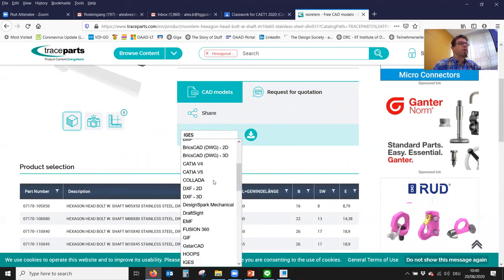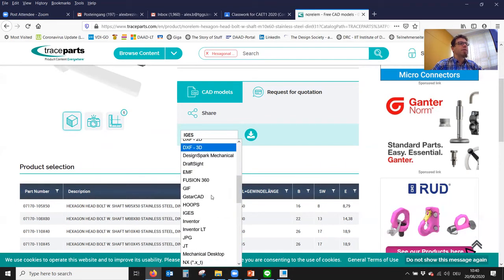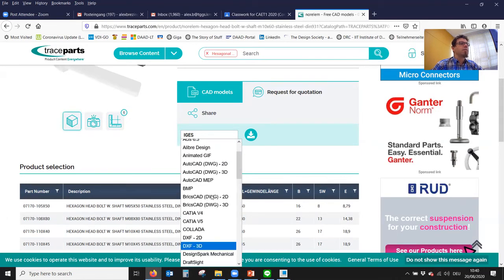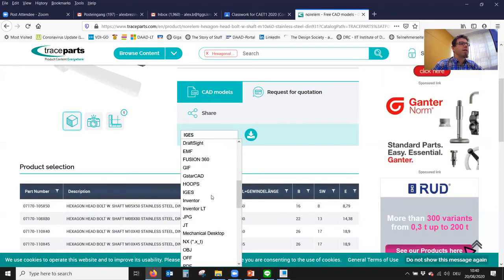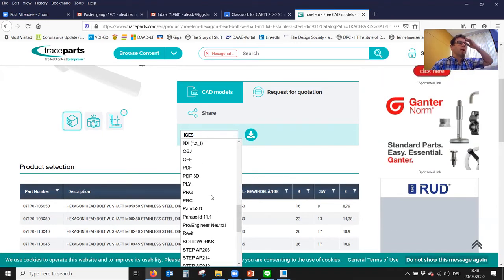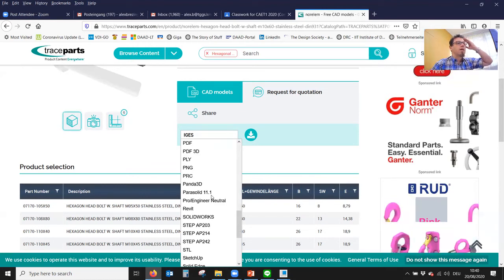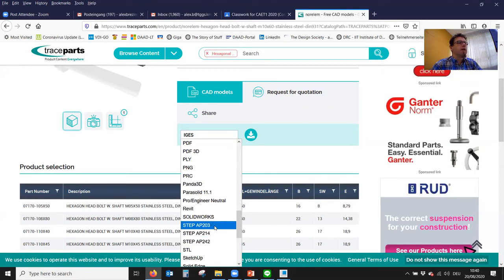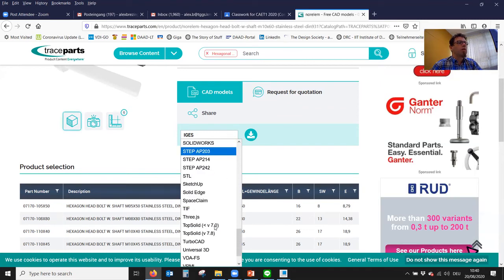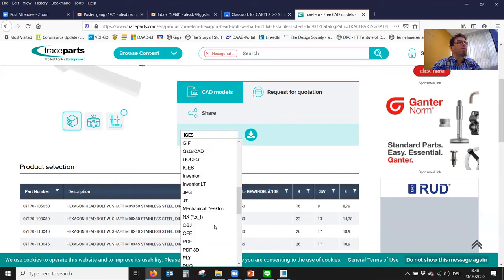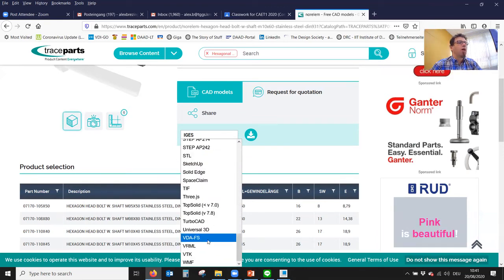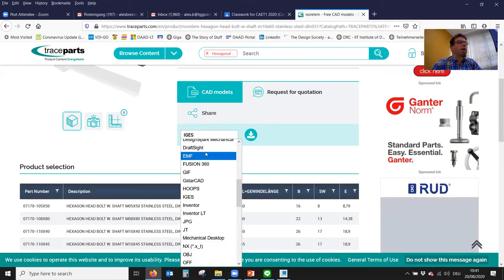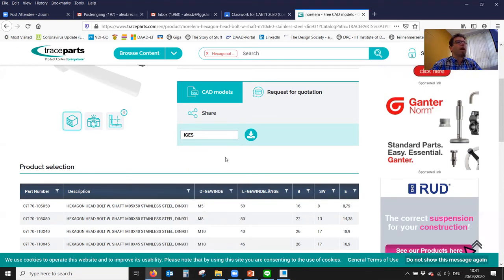What I also read, what is a good standard for mechanical engineering is STEP. So STEP or IGES, actually STEP is even more reliable if I can find it. Of course, there are way more. Oh no, they have different versions of STEP. I'll just try this one, AP203. Oh, I don't know what that is. You know what? You can try that. VDA works great too. VDA is the automotive industry standard. JT is also a standard you can use, but I just use the good old IGES.